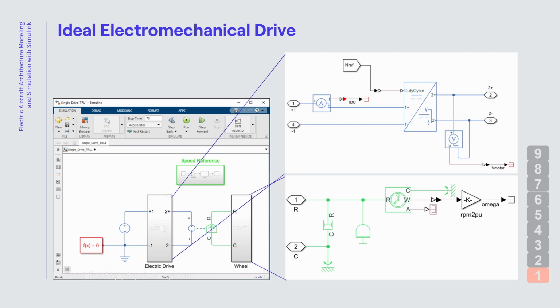This is our lowest level of fidelity, where the relationship between voltage and speed and current and torque is defined by a constant proportionality. With this model, we set a DC voltage level using an average value converter with duty cycle input. The duty cycle relates to specific voltage and hence specific speed, and so we need no feedback control for the speed control. With this model, we can set larger time step to achieve fast simulation, but we only gain high-level information on voltage and current, and we have no specific technology characteristics. We can regard this model as TRL1.